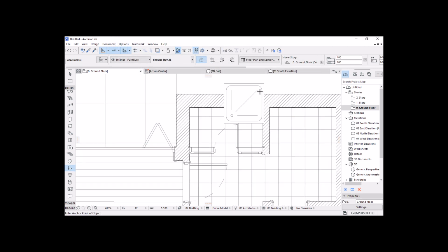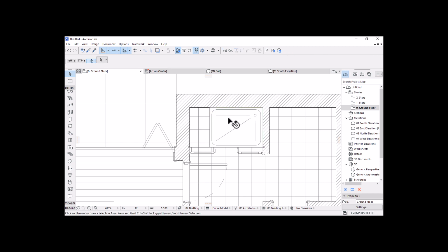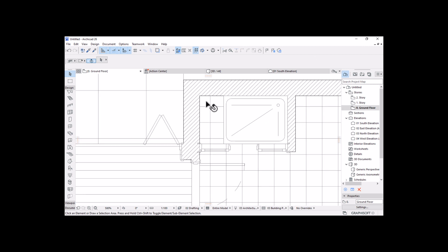Let's place our shower there and make sure we rotate or mirror. I'll pick this point and then mirror like vertical, and then mirror again horizontal, yeah, and then pick this point, move it to the corner there, and let's make it 1200 millimeters. I want to leave a space for more like a bench here, so that someone can just sit again and do more like a sauna kind of.